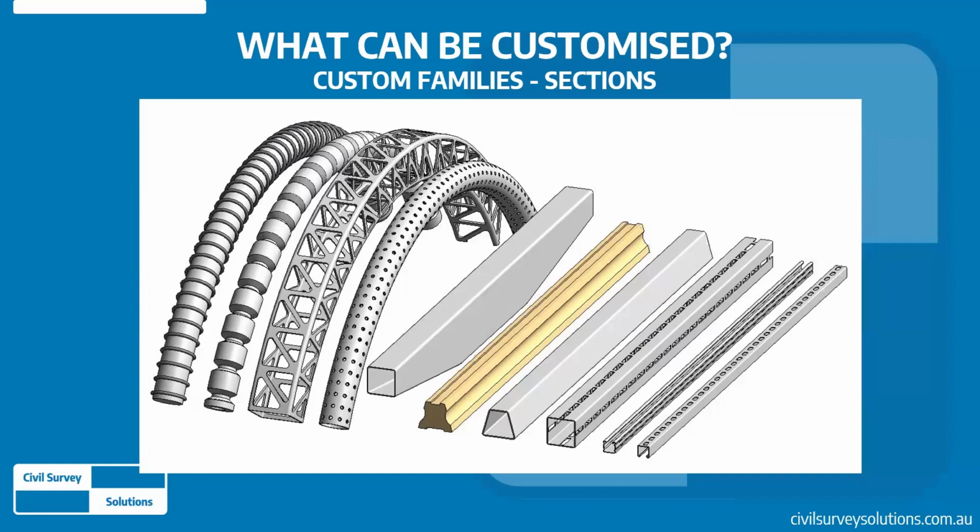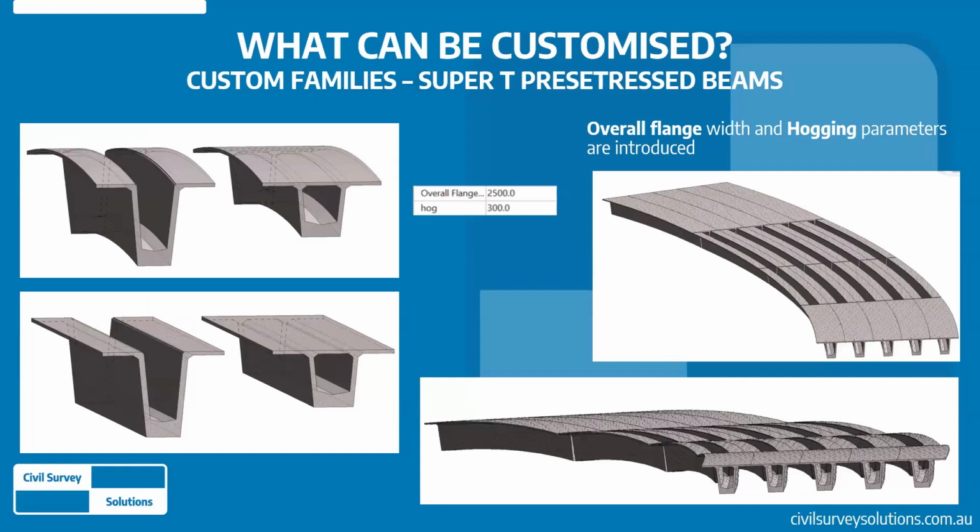Now, I'd like to talk about a few custom families on the next slide, which I have created and developed here, which is the Australian Standard Super T pre-stressed beam. We have already included all the standard Super T in our custom template. And also, as you can see in the middle, the overall flange width can be controlled with an instance parameter, plus some hogging capability. If you just type in how much hogging is going on, you have that flexibility.